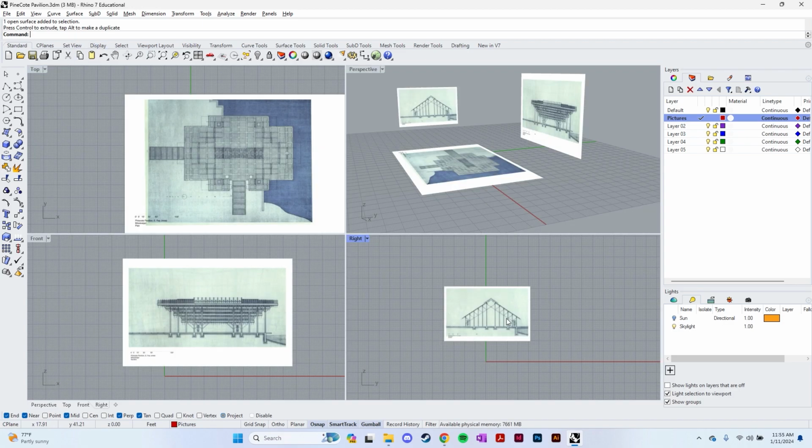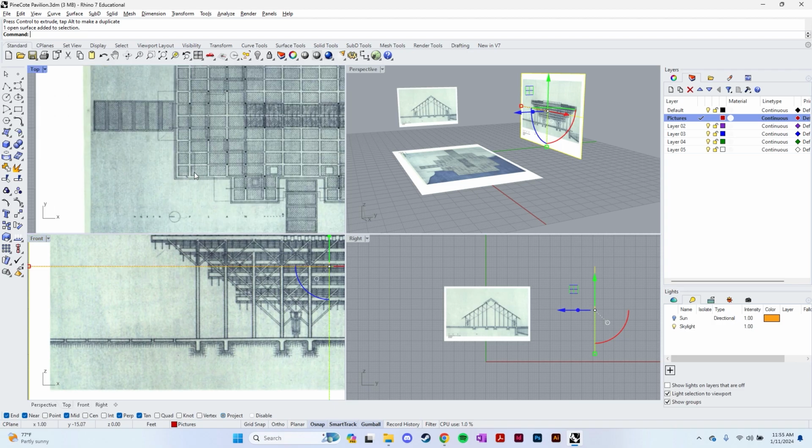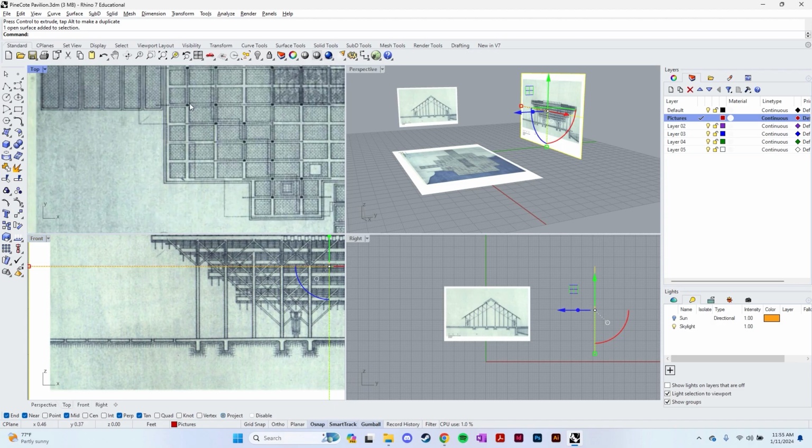So now we need to line all of these drawings up so that when we work in this 3D space, we're kind of working on all of these drawings at the same time. To do this, we're going to choose a reference point. This can be like a column base or something. So looking at this plan drawing, I'm going to pick this column to be my sort of 0, 0 reference point. And I'm going to find that column on every single drawing and sort of line the drawings up such that when I draw something starting from 0, 0, all of the drawings kind of snap there.